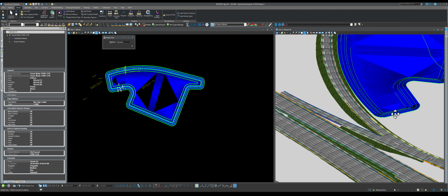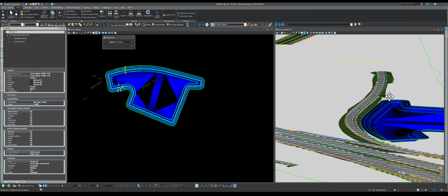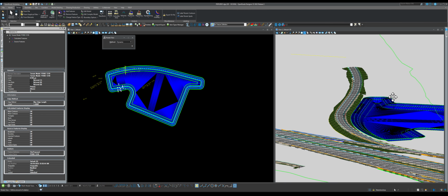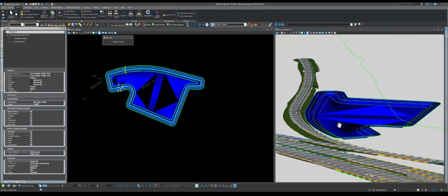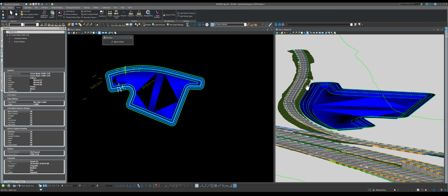But we still have not jumped into a template, and before we do, there are a few things that you can do to make the roadway like you. What you need to do is see where the roadway is going to need connectivity with you. As you can see here on a pond, the roadway would want connectivity with you on this side of the pond, meaning here. So technically, if they just have a corridor here, they're going to make their life easier, and also your life easier too, because they can connect with your corridor or you connect with their corridor.